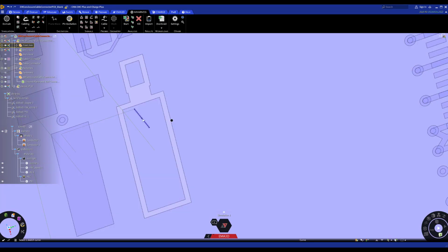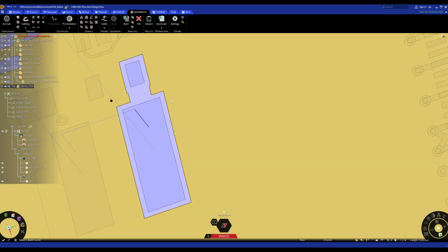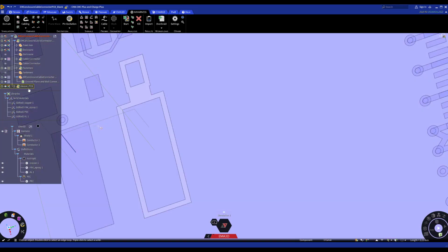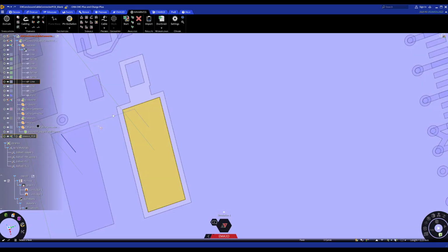To do that, the easiest way is that we select this wire, right-click, and assign line material to be PEC. Similarly, we can select this wire, right-click, assign line material, and select PEC. Or we can do this from here by expanding the free lines, selecting which one of those, and thus define the material. Now we want to define the current source here.